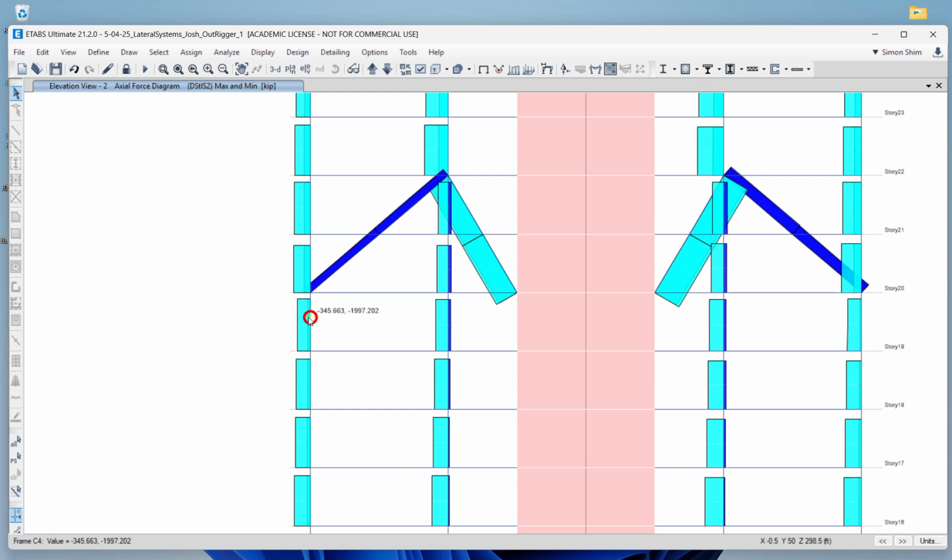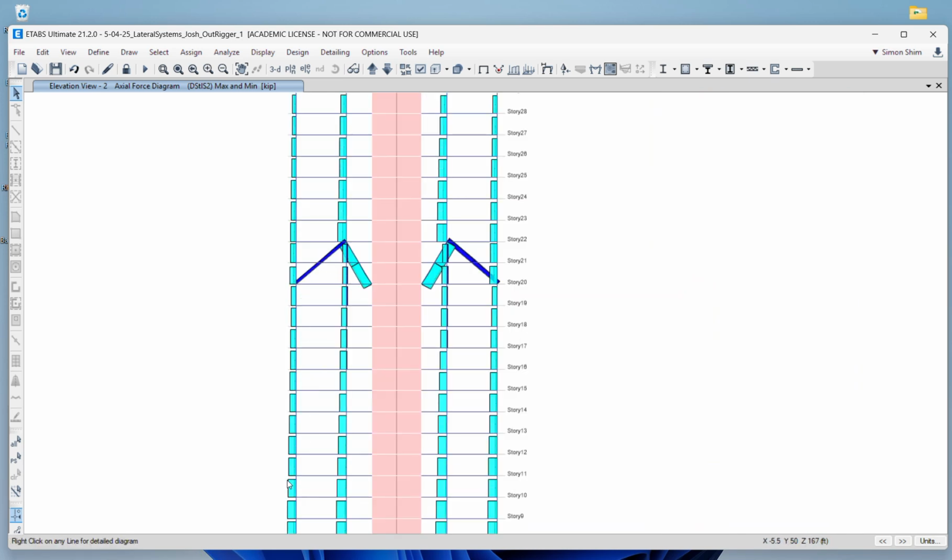So this is what I think is a limitation of this model. So first, we need to go back to the previous model without diagonal, right? Without diagonal, you design the column based upon all gravity load, and then come back with the diagonal. Then we need to adjust the column, right?